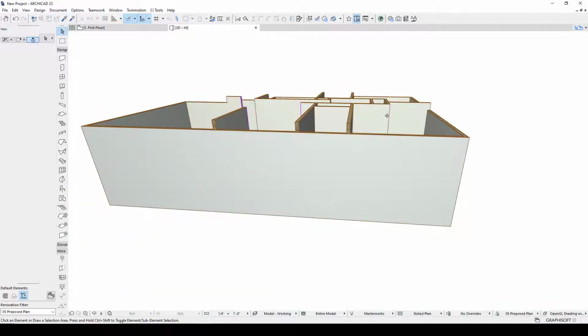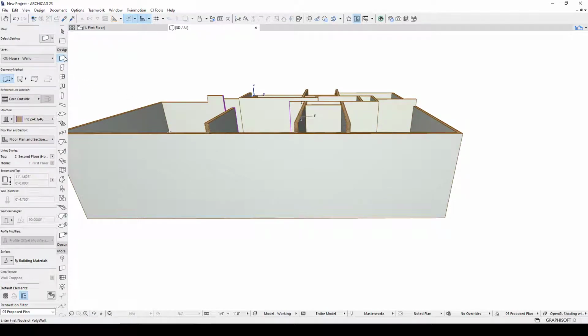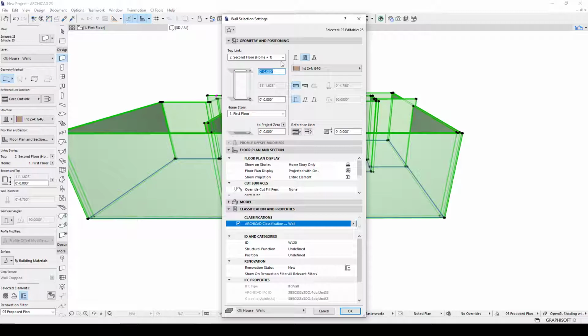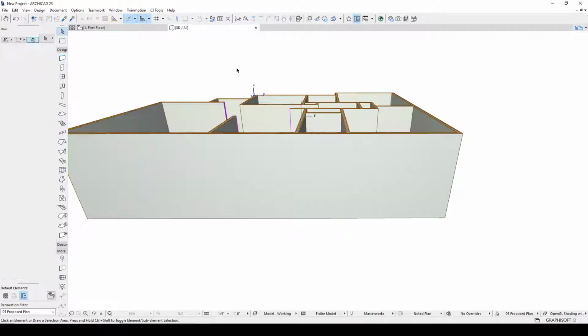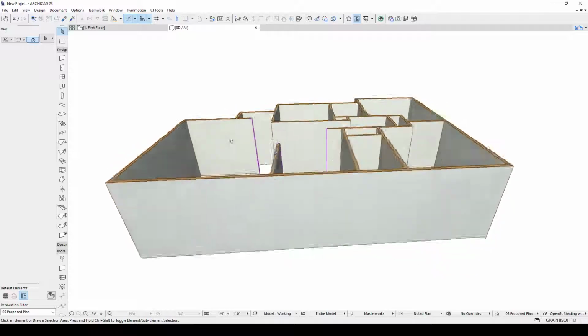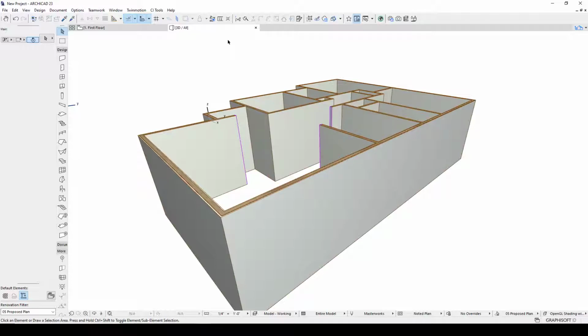Notice our interior walls were not set to the right height. That isn't really a big deal. We can just hit wall, Control A, hit apostrophe, or double click this. And here we want to set that minus 12.625 inches. Now everything is 10'1". Great. Okay. So that gives us all of our walls. And in the next video, we'll throw in some doors and windows.